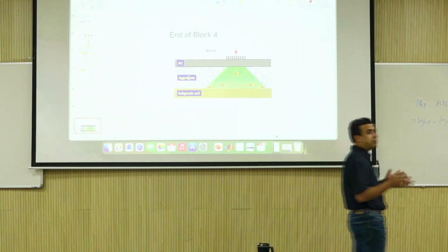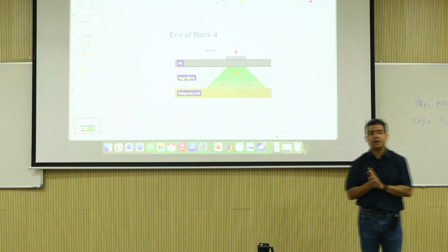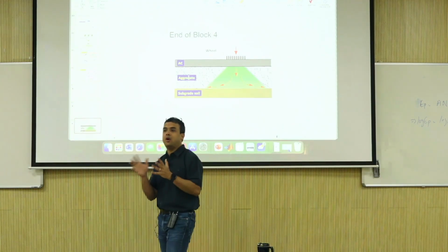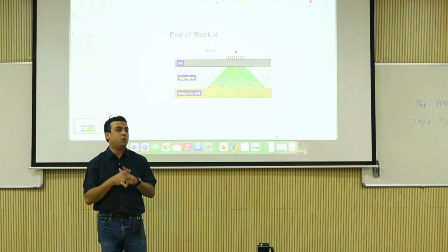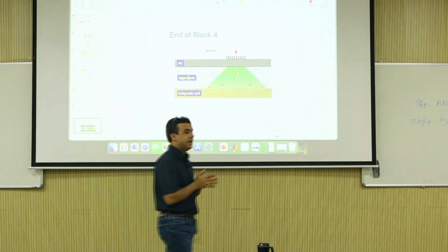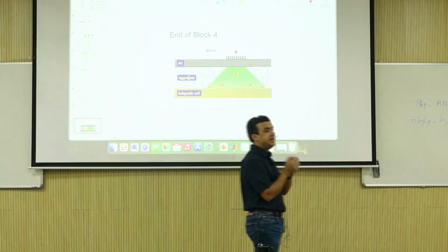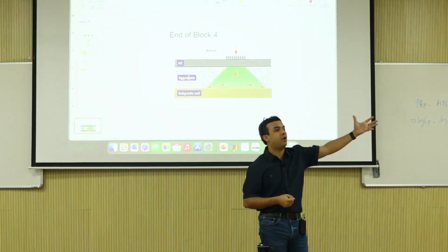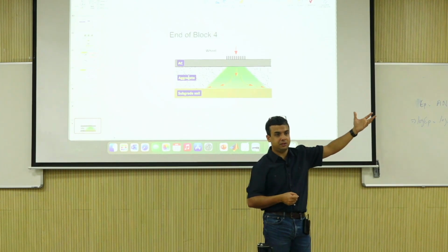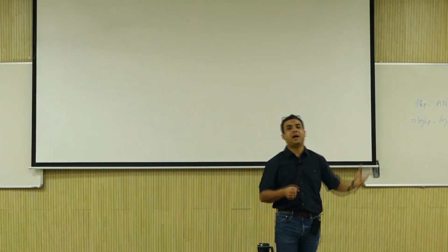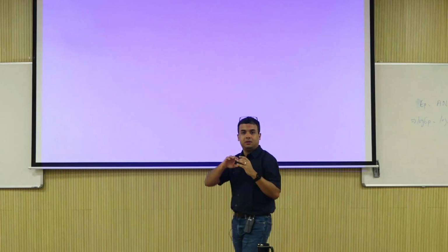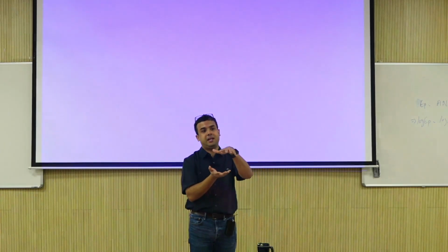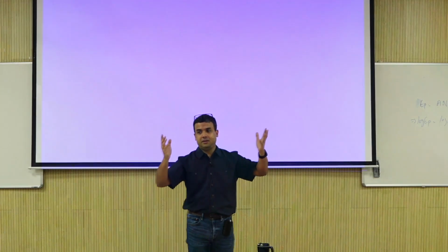Then we talked about the models and stuff. Resilient modulus, we talked about different models, how to fit the model, what the models mean and what not. Why is that important? Because that gives you an idea to take any stress state and predict a modulus for that material by using the model. Otherwise, you cannot have an idea about the modulus of a layer because it's stress dependent.